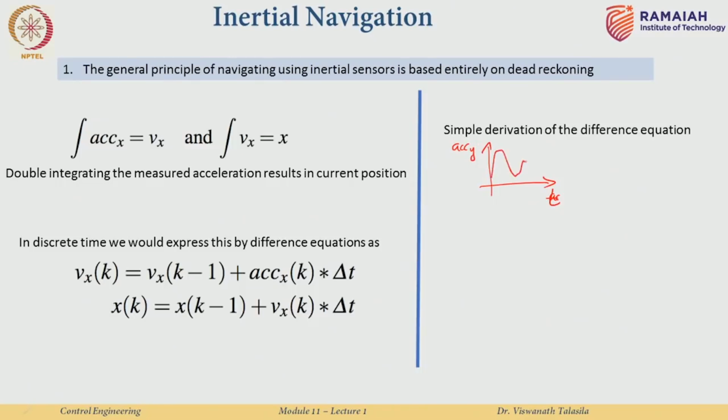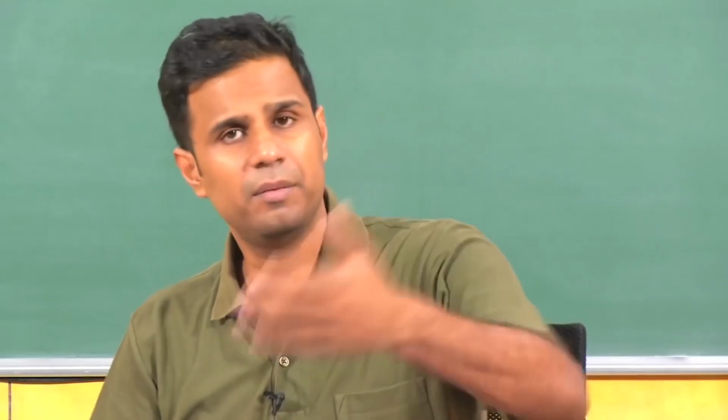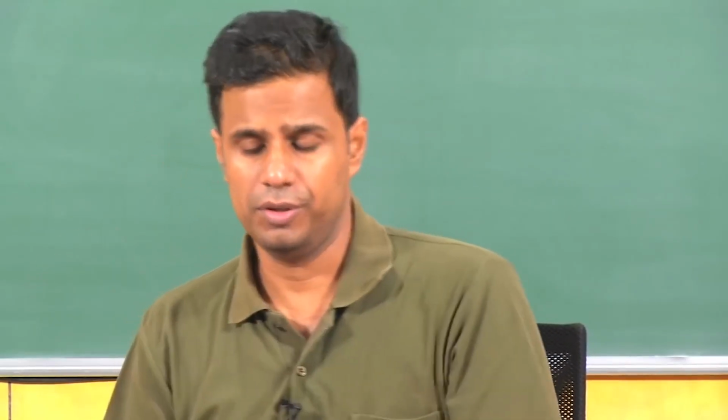So, let us say the vehicle was accelerating in that particular manner. Okay. When you actually try to connect this sensor to a microcontroller, you need to pass it through an analog to digital converter, right, and depending on the resolution of the analog to digital converter, you actually get a 16 bit, 10 bit, 8 bit, and so on and so forth, right. So, the accuracy increases with increasing resolution.